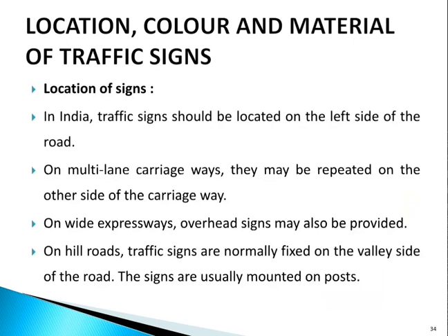On multi-lane carriageways, they may be repeated on the other side of the carriageway. On wide expressways, overhead signs may also be provided. And on hill roads, traffic signs are normally fixed on the valley side of the road. The signs are usually mounted on posts.